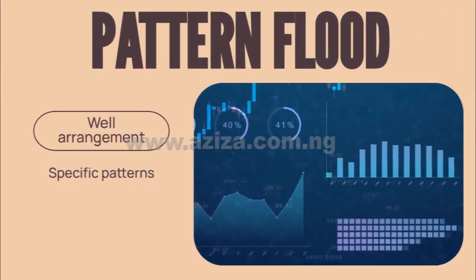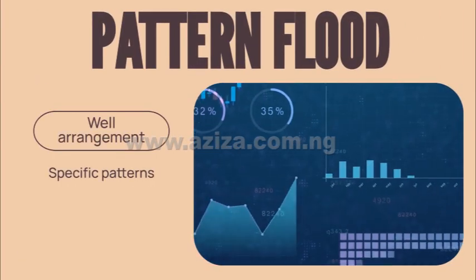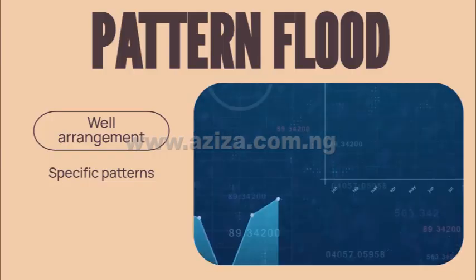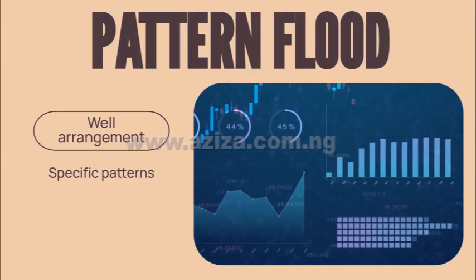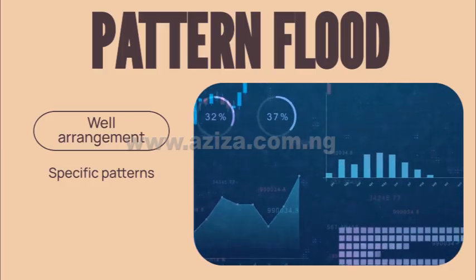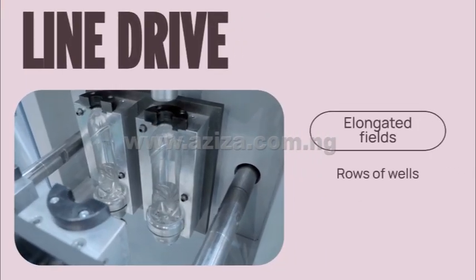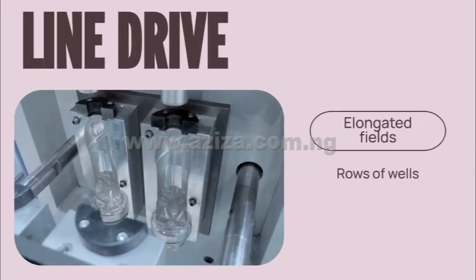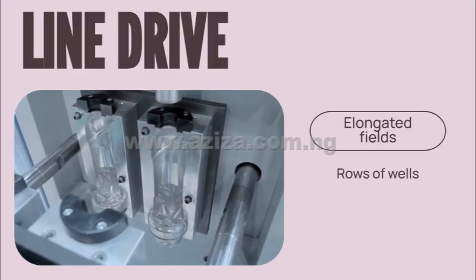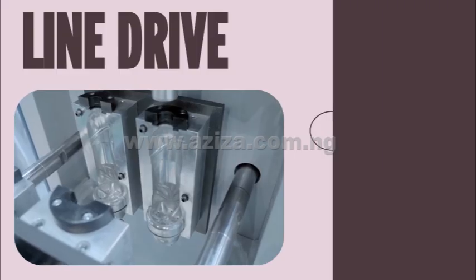Pattern floods, such as the 5-spot and inverted 5-spot, involve a specific arrangement of injection and production wells. The 5-spot pattern has one injection well surrounded by 4 production wells, while the inverted 5-spot has one production well surrounded by 4 injection wells. These are popular for more uniform reservoirs. A line drive pattern consists of rows of injection wells facing rows of production wells. This pattern is often used for elongated reservoirs or when there's a strong directional permeability in the reservoir rock.